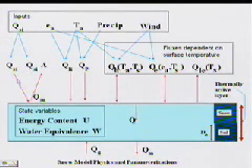The net radiation is the incoming radiation minus what's reflected, which is the incoming shortwave times the albedo. The incoming long-wave radiation is calculated based on the air temperature and the humidity. You probably learned last time about black body radiation and the principles of emissivity. And the emissivity of the air is usually related to the water vapor content. Then the heat that's brought with precipitation is related to the precipitation and the air temperature.